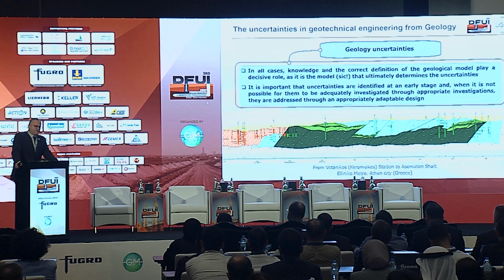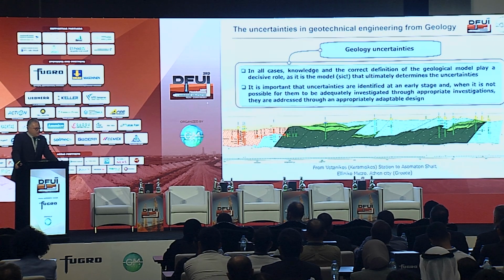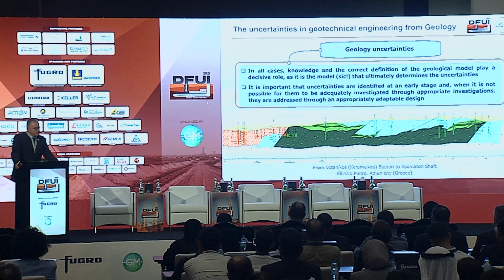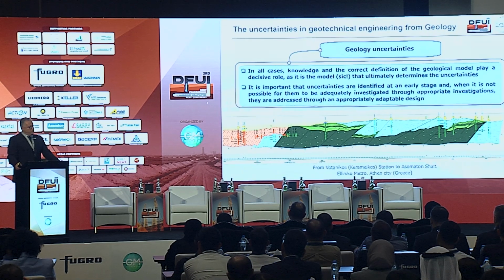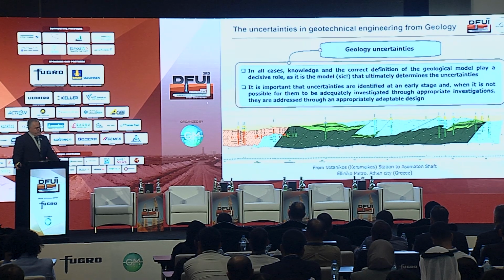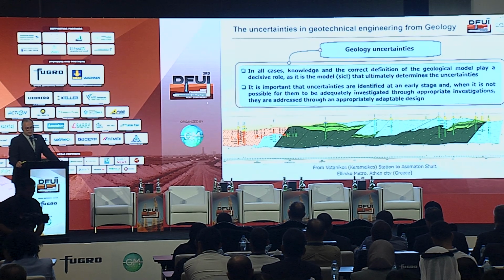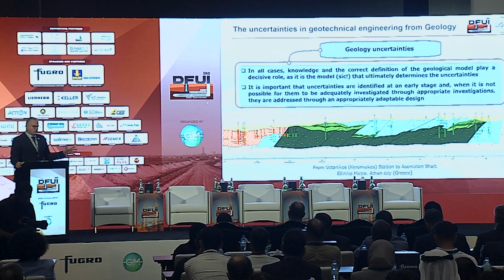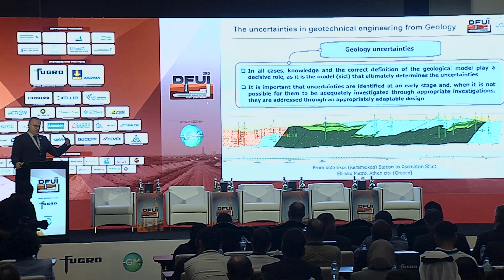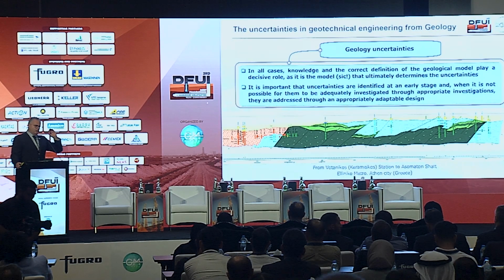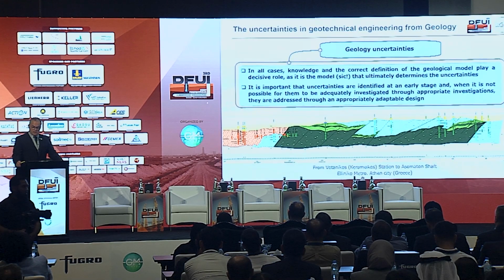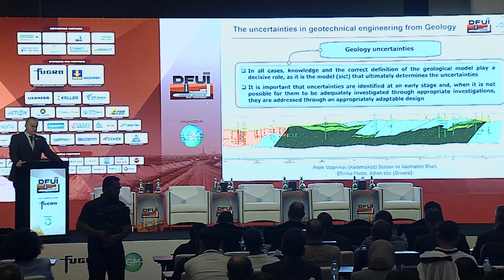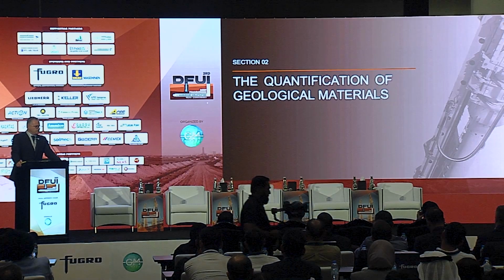If we don't have the time or the budget for a very detailed ground investigation program in order to have a very strong geological model, then we really need to have an appropriately adaptable design. So what we ask from the geological model is not only what we are expecting, but also, in 3D, to identify all these uncertainties. So it's a pretty big task.